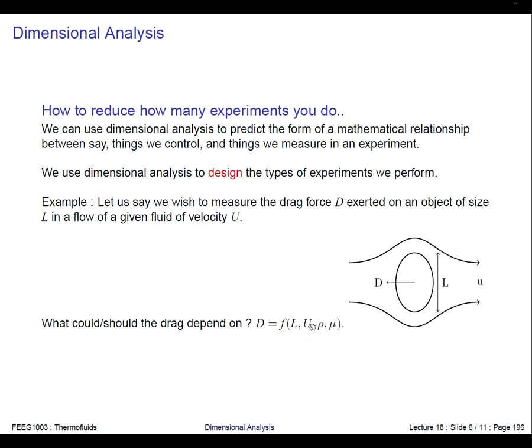And it turns out that this parameter is non-dimensional, and what this allows us to do is when we get our results, we plot it in a non-dimensional way. So my y-axis has no dimensions and my x-axis has no dimensions, and this allows me to plot experiments where I used completely different fluids on the same figure, and make that data useful.